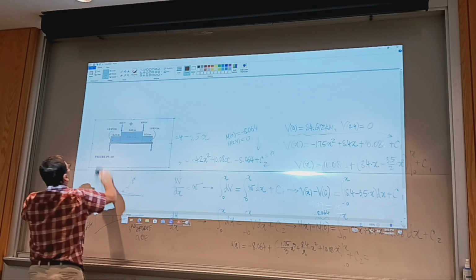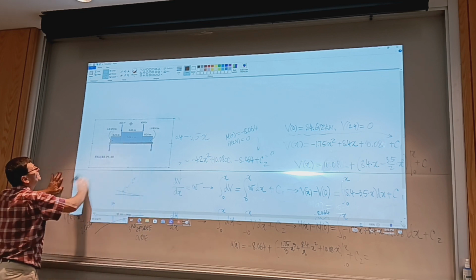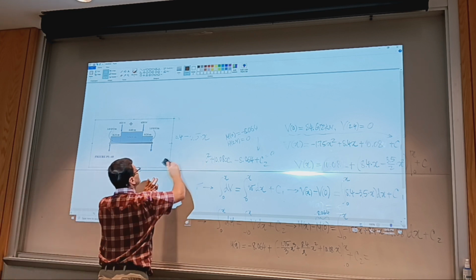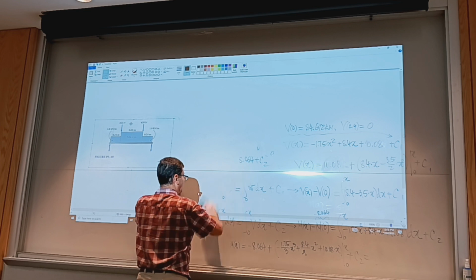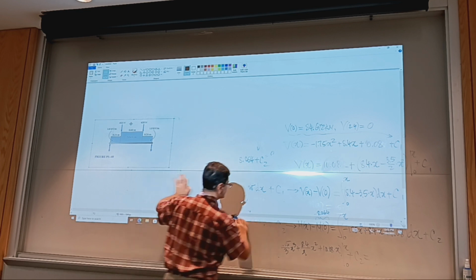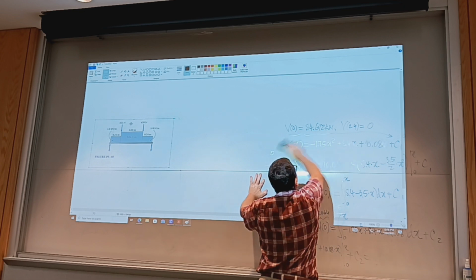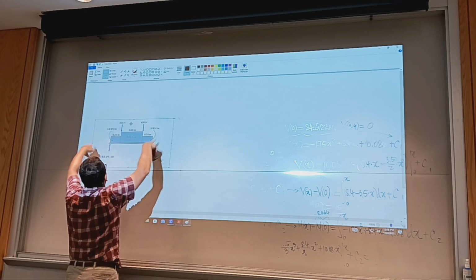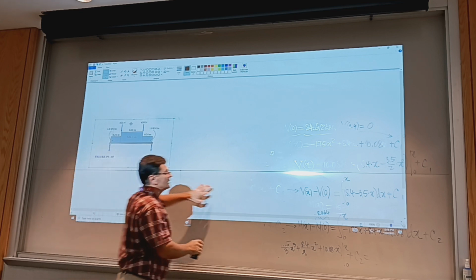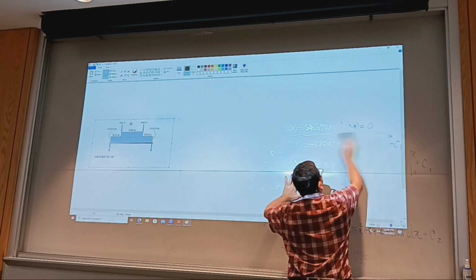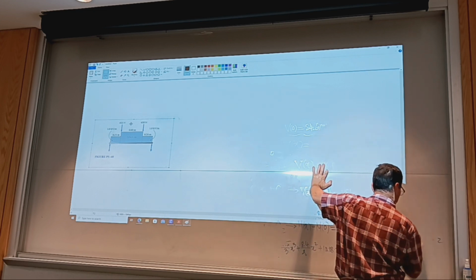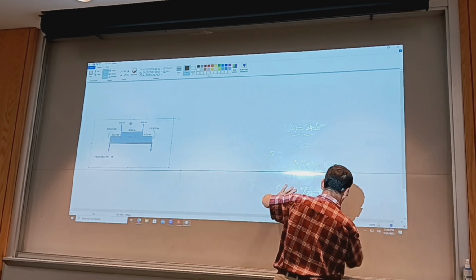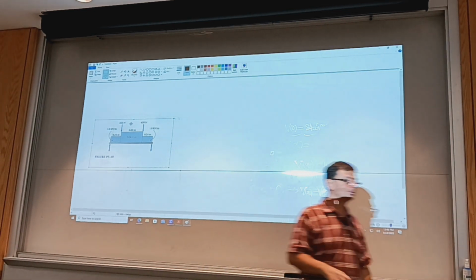Okay, so in addition, we have concentrated moments, as you can see. But this beam has symmetry. So we're going to exploit the symmetry, save us some calculation time, right? So on one hand, the moments are equal and opposing. So they don't condition the reactions of the support. And then the distributed load is symmetric and the concentrated force is symmetric.